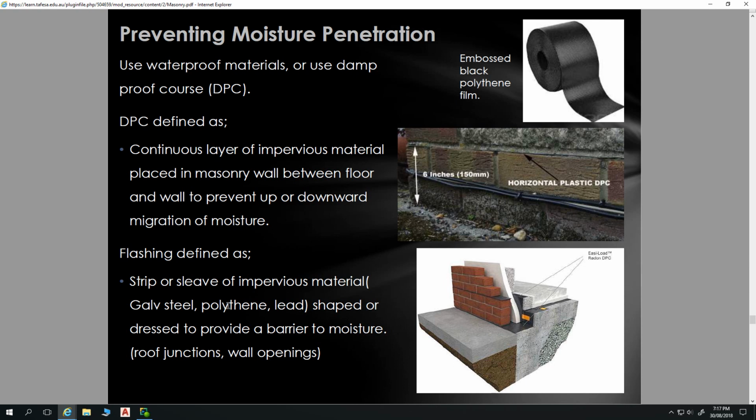So it's embossed, so it beds in well with the mortar. That just goes in under your bottom layer of brick to stop any moisture coming up. It's also typically laid in your bottom layer of brick, and then you have a weep hole above it, and then you carry it up and nail it to your timber stud, so that any water that comes down inside of that brickwork hits that flashing at the bottom and goes out the weep holes. But it is essential that it is put into the brickwork to stop the moisture coming up.